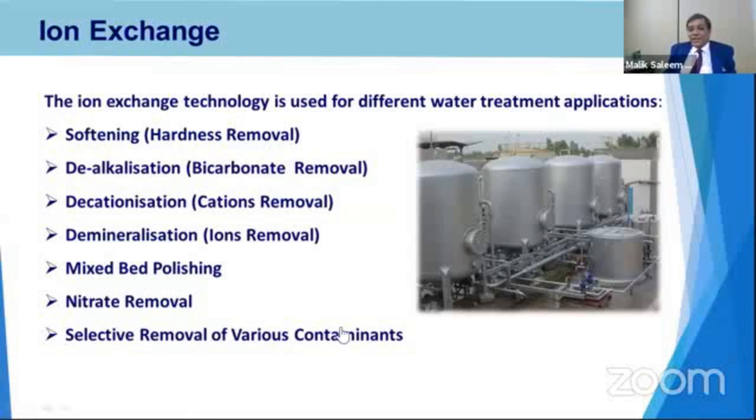Inshallah, we will discuss this in our ion exchange module. You can see these are pictures of the softening plant. We have a battery of softening plants which we installed at TNB Liberty Power in the Sindh area of Pakistan, and they are 90 cubic meter per hour automatic softening plants. And you can see this is the brine tank with which regeneration of the resin is carried out.